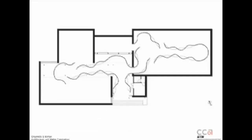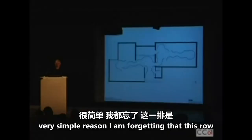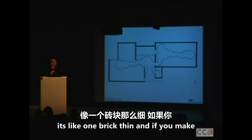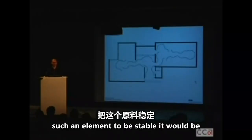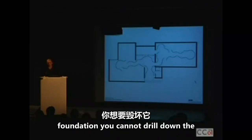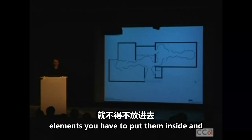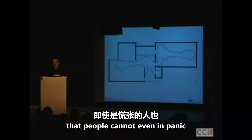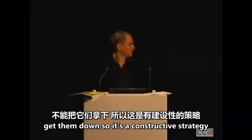This is for a very simple reason: this wall is produced in elements. This wall is very thin, just 1 brick thin, and if you want such an element to be stable, because in the pavilion you have no foundation, you cannot drill down the elements, you have to make sure that people could not, even in panic, tear them down.